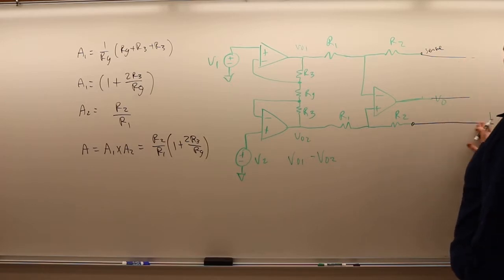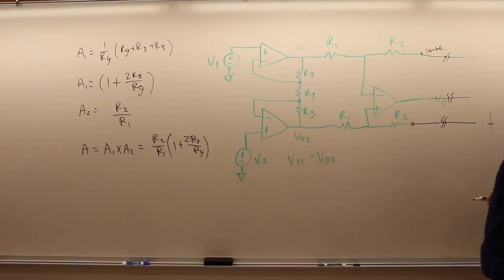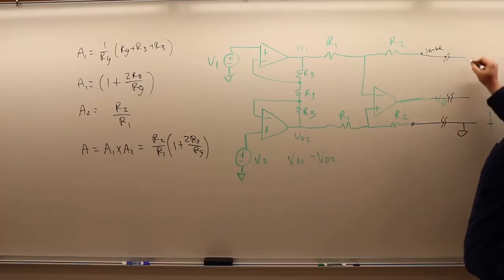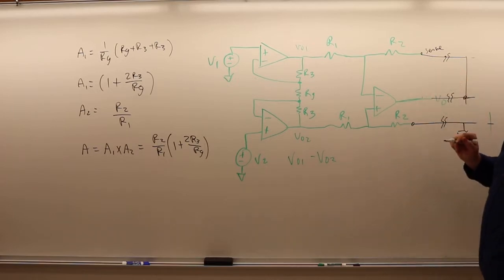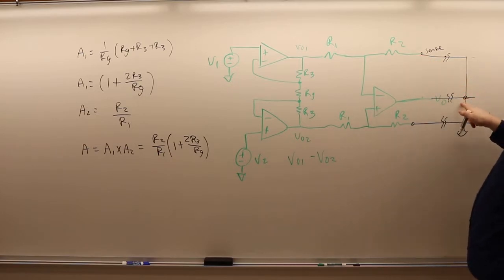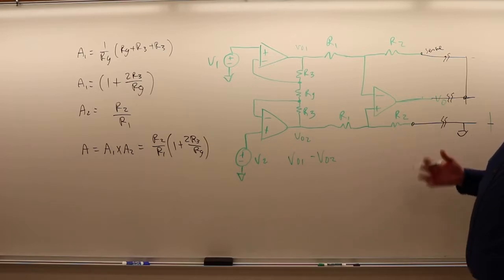So whatever distance this has to travel, we'll draw a little something to show that this actually travels some great distance. The user is then responsible at their end for connecting this to ground and connecting these two signals together to provide their output signal. What's the advantage of doing this? The advantage is that it allows you to connect this point of this resistor to your output signal, wherever that output signal is. It allows this circuit overall to compensate for parasitic resistances or noise that might be injected into this.